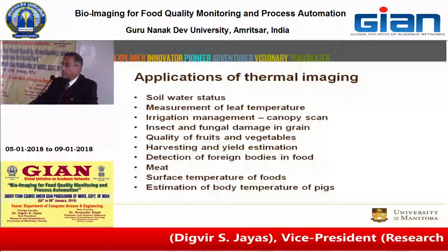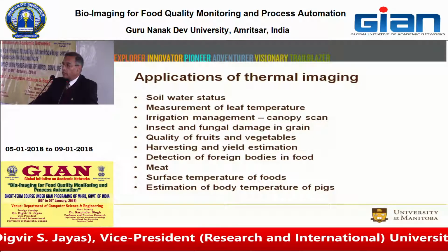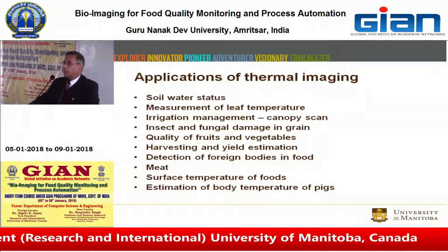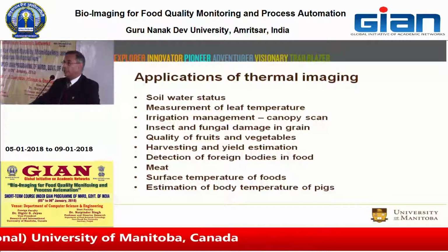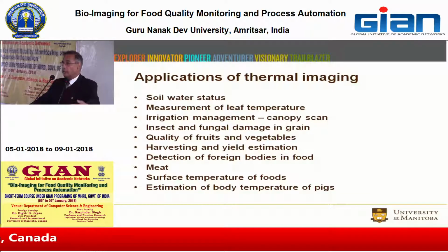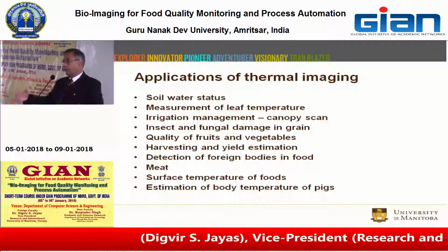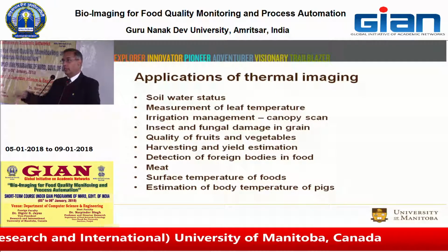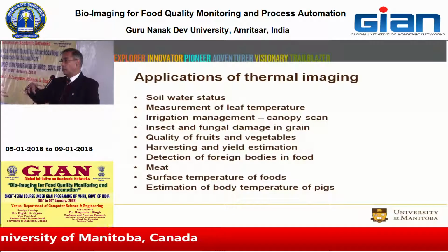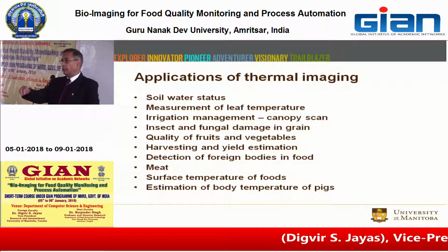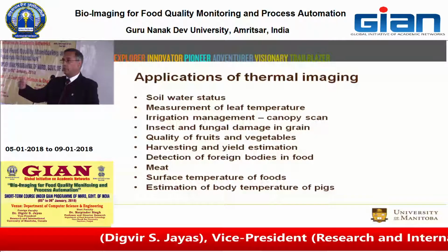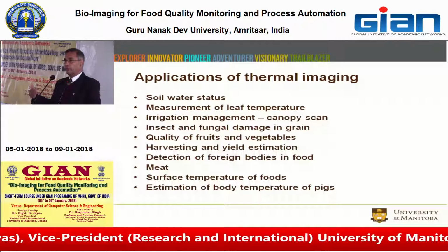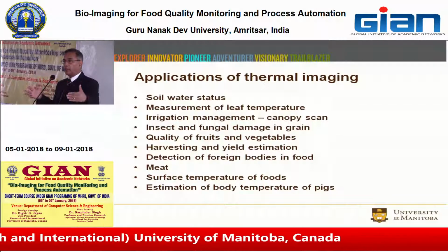The one thing to keep in mind is that it is a surface temperature measurement phenomenon. It does not measure the temperature inside the body. So to give you an example, in a large, let's say, grain bin, if the grain is spoiling in the middle of the bin, it would not be able to detect that grain spoilage in the middle of the bin, because the amount of time it would take for the heat to move from that spoilage area to the surface would be quite long, because grain is a very good insulator.